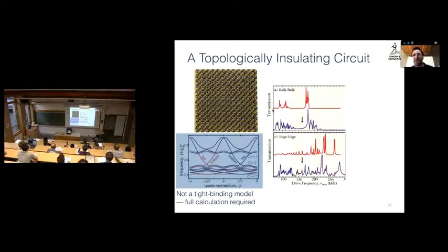But the basic idea here is the following. You can inject a signal into a particular lattice site in this circuit just by putting a little magnetic coil above one of these inductors and coupling to it inductively, okay? And then you can measure a signal at another lattice site with another coil, okay? And sometimes we do one inductor, sometimes we excite a pair of inductors with the appropriate phase to excite a particular spin state, okay? But the picture you should have in mind now is we can really make a scanning tunneling kind of microscope to see the microscopic behavior of the system.